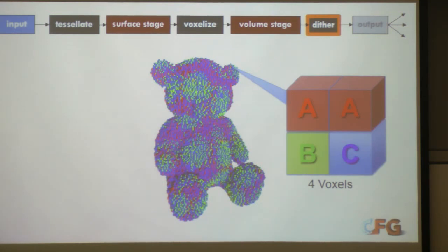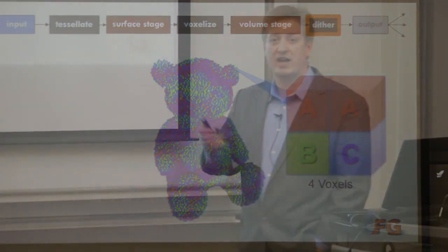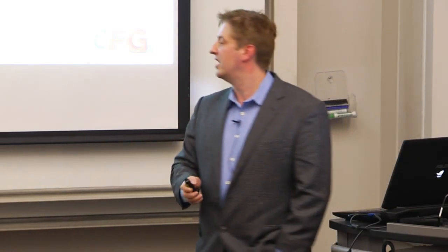In this case, most of the current printers really cannot handle continuous material composition. They have to put some particular material at a given voxel. So in order to handle our abstraction, we have to take this continuous input and distribute it locally. This is very similar to the way we do 2D printing, where we specify the colors RGB at some resolution, and then when we actually print them, we have to assign some given colors.